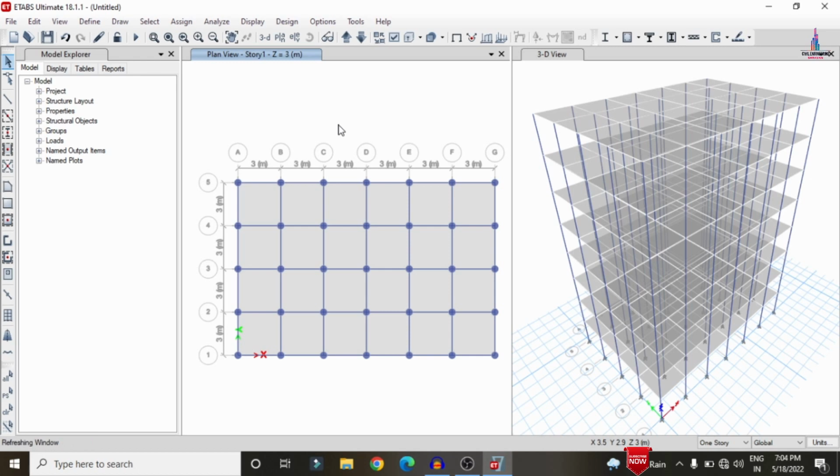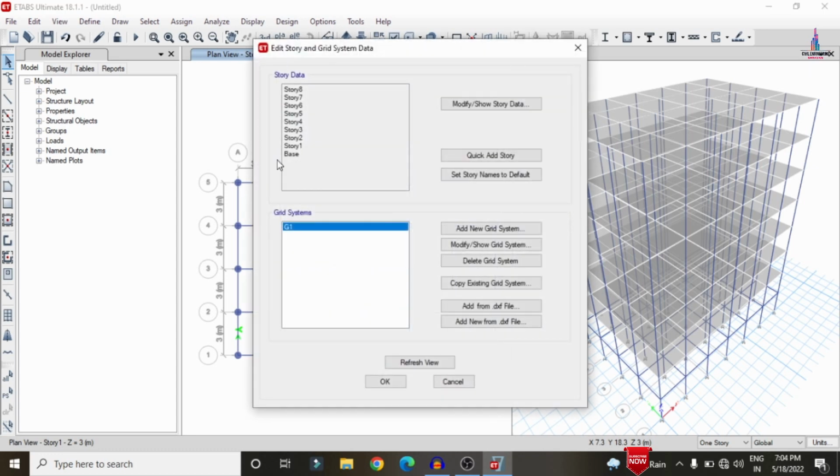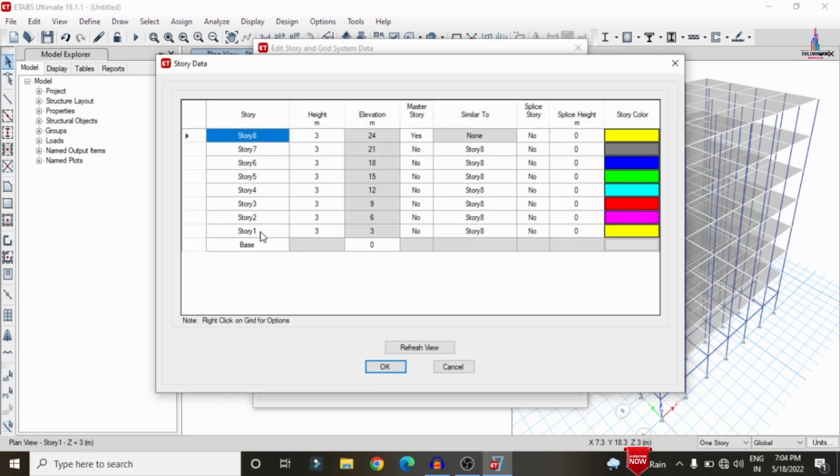Okay. So now we have to edit the story number and height of the story as per our consideration. I am selecting modify here. You click on the modify option. Select this particular section to the plinth. I am selecting G. This is the 1, this is the 2, this is the 3, this is the 4. Again this is the 5 section and this is the 6 section.